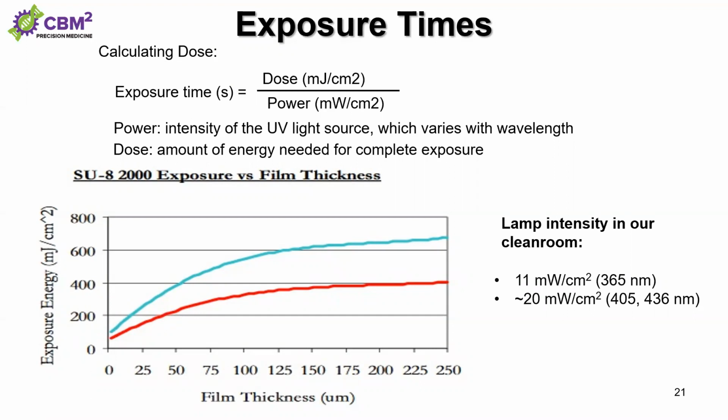Again, that curve also shows the exposure energy as a function of film thickness. So when you determine the dose, you also have to think about the thickness of your photoresist layer as well.